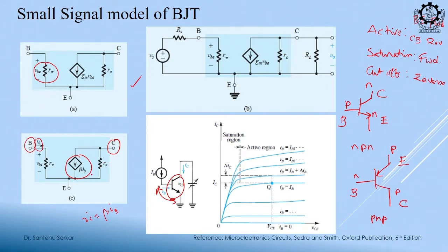And as we modeled, output is current here, this is a current model. So, this output resistance should be in parallel. We are denoting it as R naught. So, this is a current amplifier model. On the input side, you see it is a voltage VBE. So, this is a transconductance model, right: input side is V, output side is current. I by V, that is transconductance; this is I by I, that is it, otherwise both are equivalent.